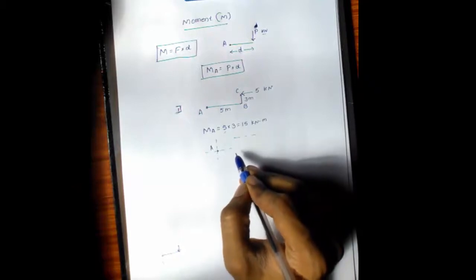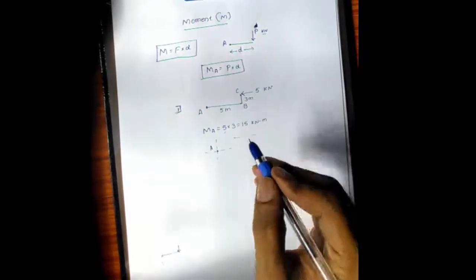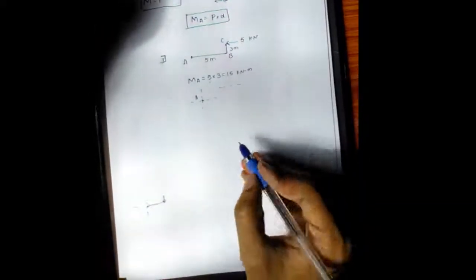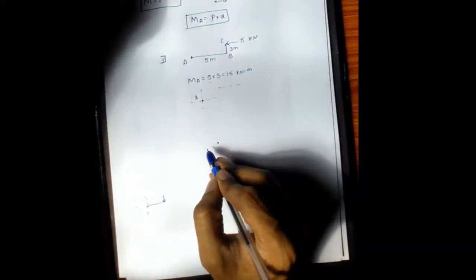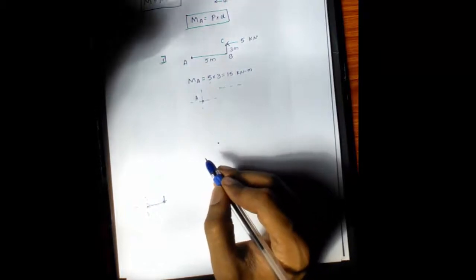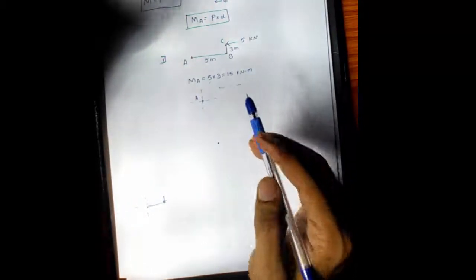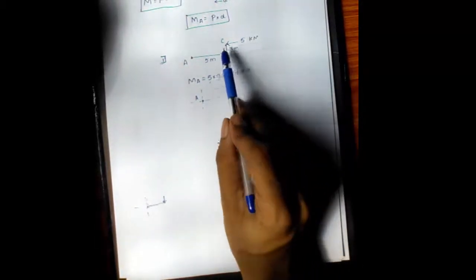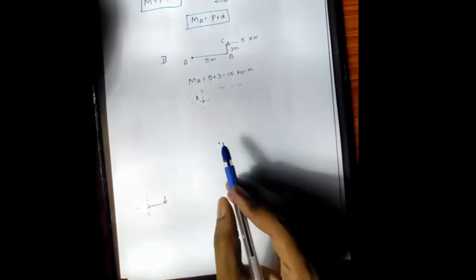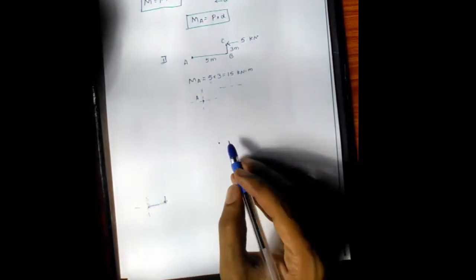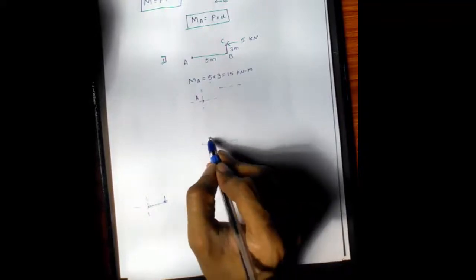Horizontal way. So to find perpendicular distance, first you can draw dotted lines in y direction also, x direction also, but you have to draw in such a way that how the force is acting. This force is acting in horizontal position, therefore put dotted lines in horizontal way at point A.